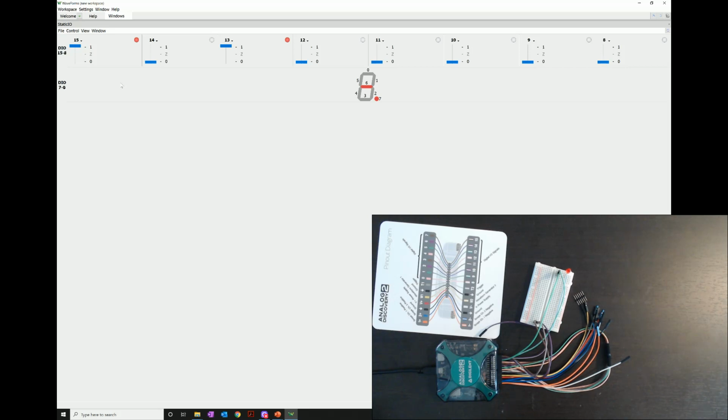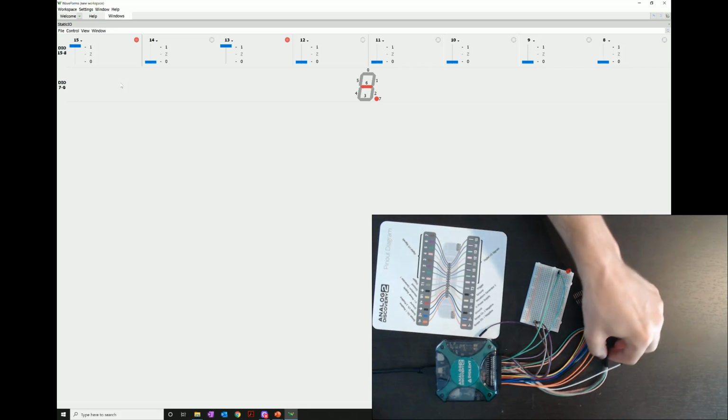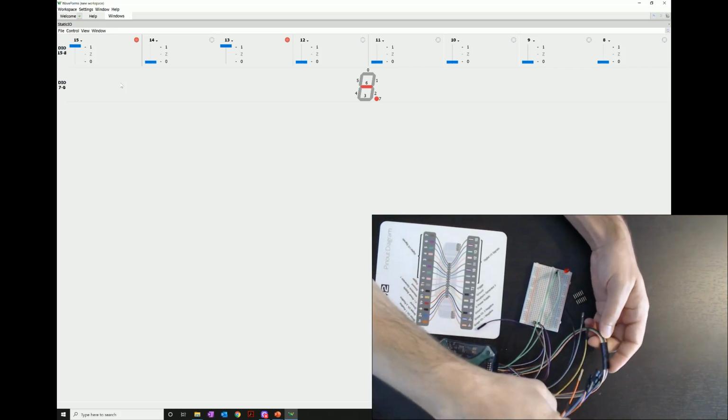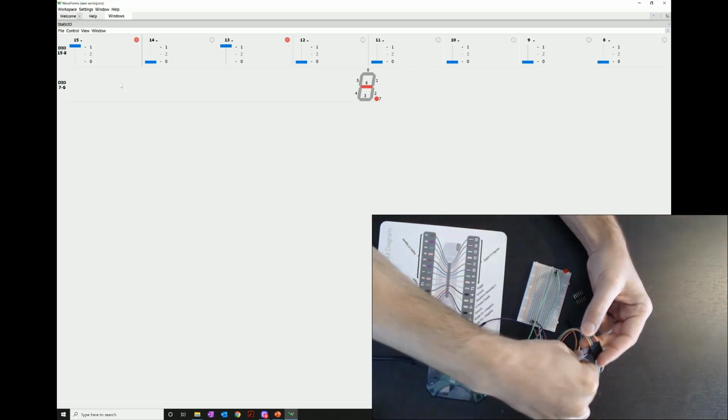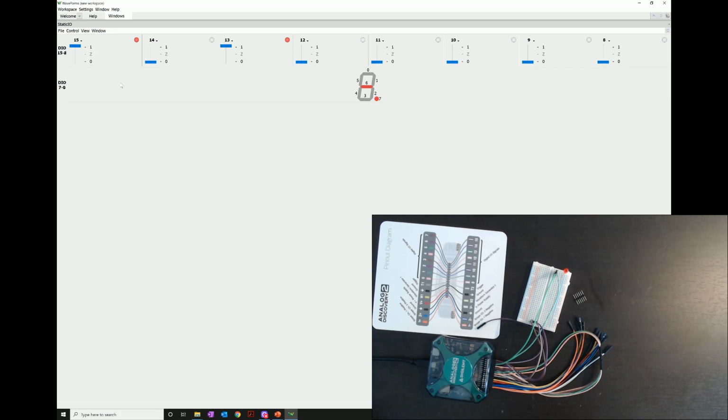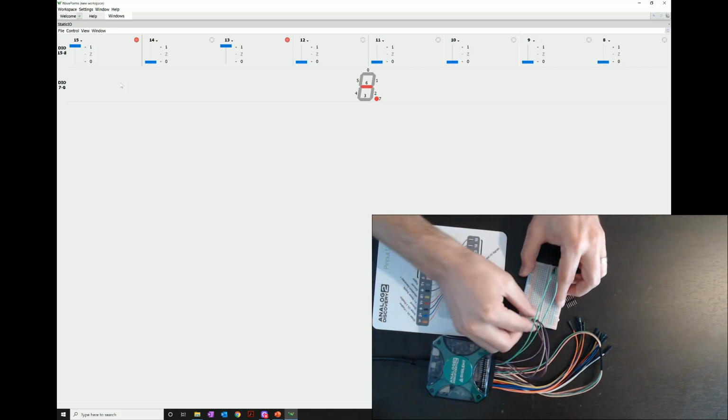And then on our AD2 board, we're going to directly connect pins 0 through 7 to pins 8 through 15, respectively. I've already connected some of our pins here, where we now have pins 0 through 4 directly connected to pins 8 through 12 using this male header. We can also connect pins 5 through 7 to pins 13 through 15 on our breadboard.